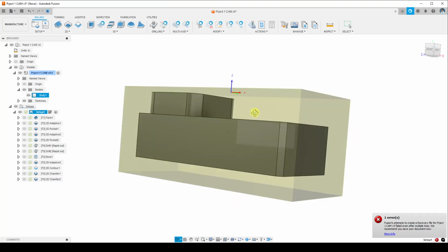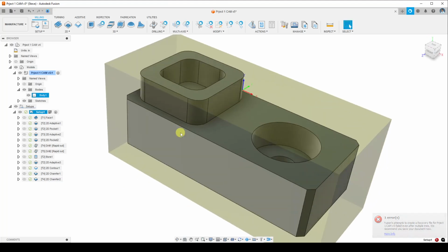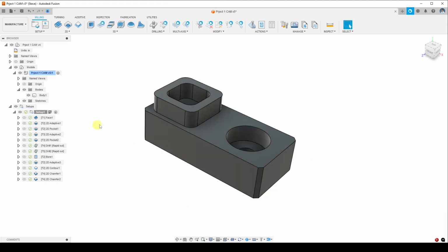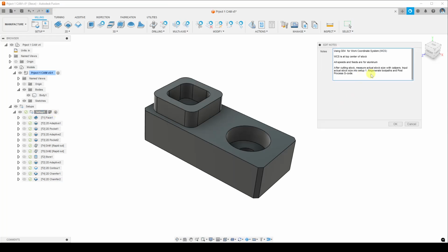So yeah, you'll need to really update that stock size. Really important. Okay, what else? Let's go back to the machining notes. And what are we going to write next? Next, we're going to say minimum part stick out equals, and I'm just going to click OK.